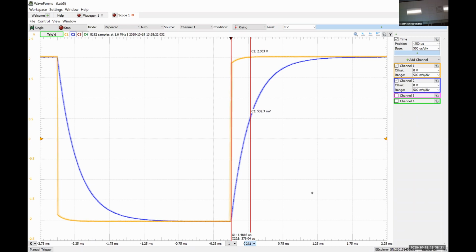So we measure the maximum value and the minimum value, and the difference between those is the peak-to-peak value. So this is a 2 volt square wave, but it's a 4 volt peak-to-peak signal because its positive peak is +2 volts, its negative peak is -2 volts, and 2 minus -2 is 4. I just wanted to be clear about that because we're going to be talking about operational amplifiers and doing a lab on them pretty soon. And the concept of peak-to-peak voltages will come up again there.